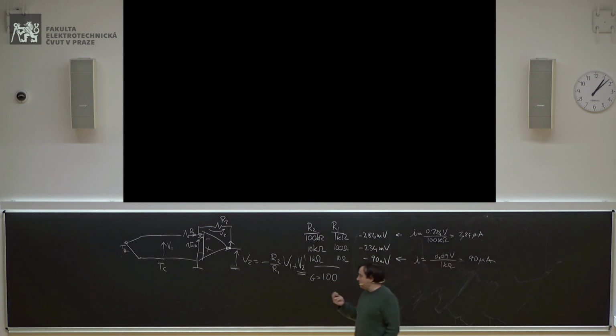And also he was mentioning the resistance changing with temperature, because again, larger current, you have Joule effect. Therefore, the resistance warms up, and the value of the resistance changes because of temperature. Again, it is true, but here we are using a current which is so small that the power released by this resistor is very, very small. So the effect itself is basically negligible. I don't know, maybe we can make some calculation. Probably the bias current on the resistor has a bigger effect.